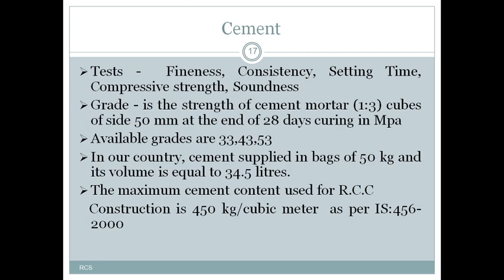And the following tests are conducted on the cement. The tests are the fineness test to know the fineness modulus of the cement, consistency test to know the consistency of cement, and setting time. Here we have two setting times, initial setting time and final setting time, and we can conduct the test on a cement mortar cube for compressive strength, and the soundness test.